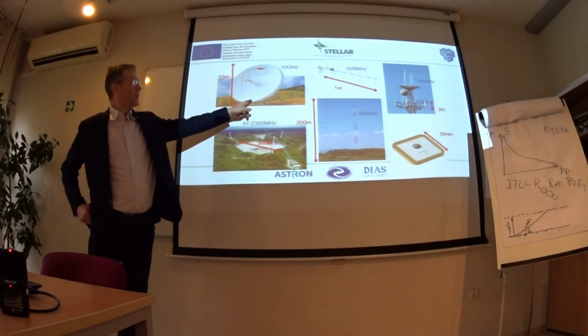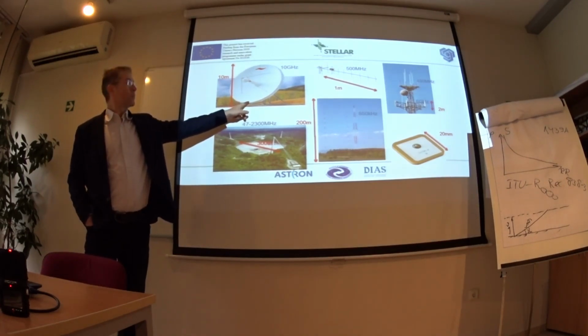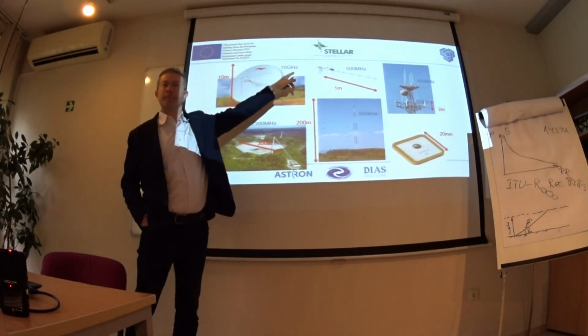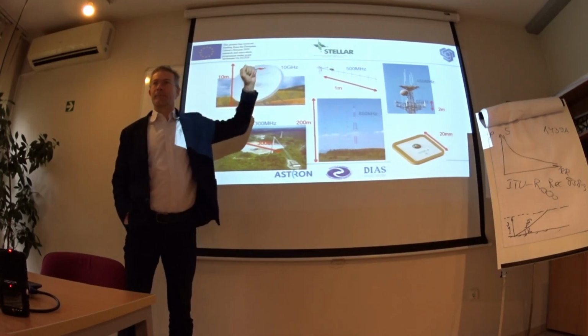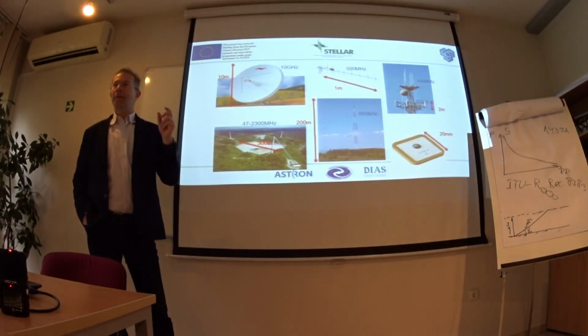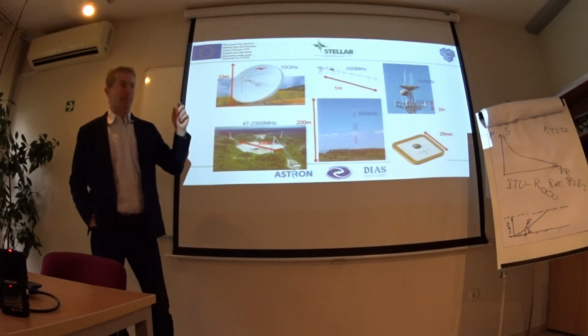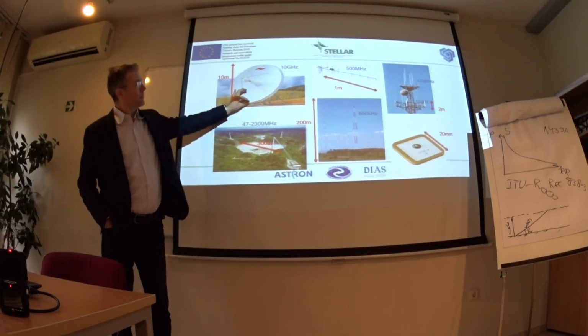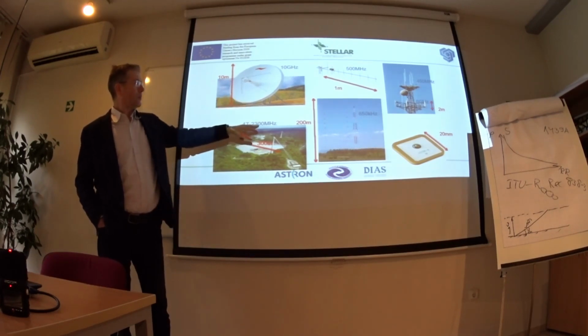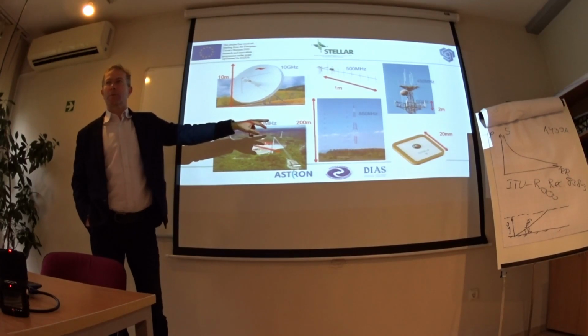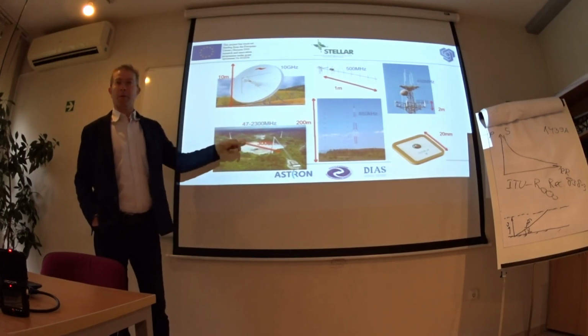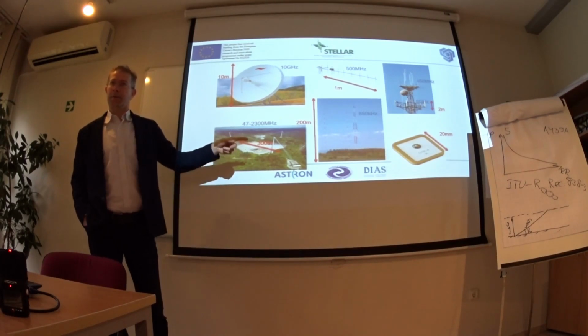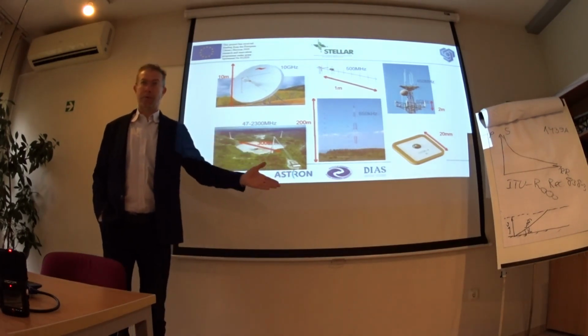So how big is the wavelength here? How long? On 10 gigahertz? Three centimeters? Close. 3 centimeters. You can barely see it. Here on 3 gigahertz is 10 centimeters, but compared with 300 meters, the aperture is much larger than the wavelength.